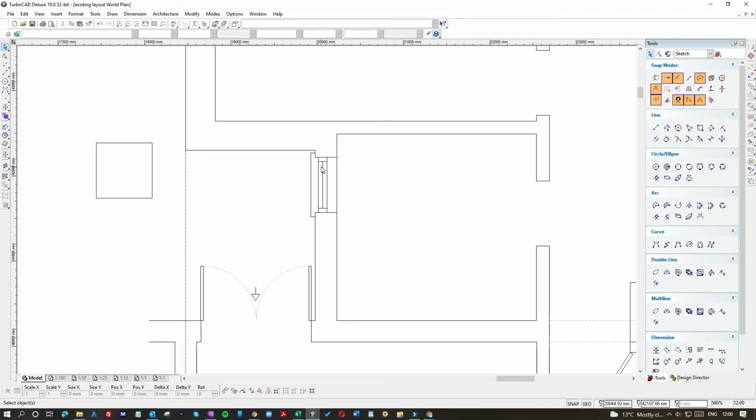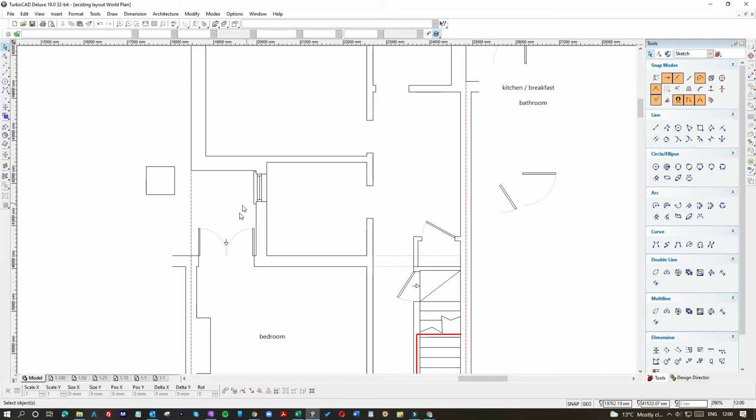So that's not a sash window. If that was a sash window, it would be sitting flush with the inside wall and the sill would be on the outside. But if it's a modern window, like a casement timber window or a UPVC window, it would sit about 30-35 mil inside from the outer line, and that's a pretty good demonstration. So that'll be obscure glass anyway, but that's the light well. So in other words, you've got a proper openable window coming into the bathroom, and we've got a set of French doors going into that bedroom.